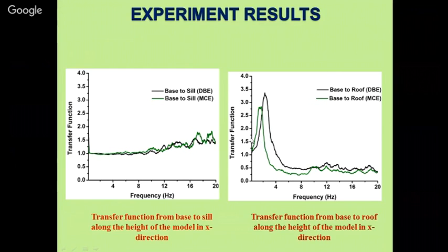This is the force. The force was increased up to 300%. But here it reduced to 50% as it reached its fundamental frequencies. So there is a drastic reduction in the earthquake forces. Here we have dissipated all the energy at a very cheap cost. So this is how we have developed this technology.